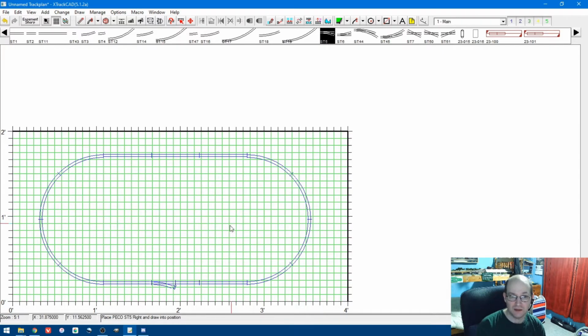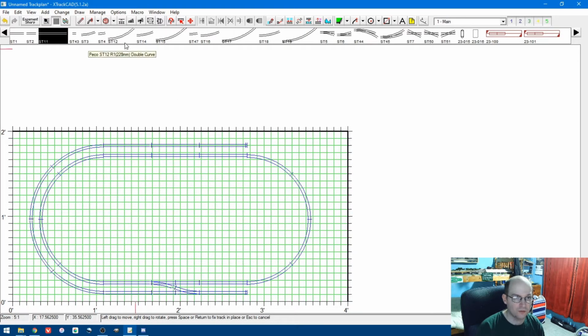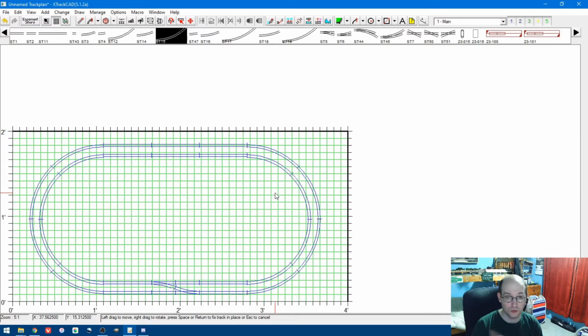You can actually do it a bit simpler way. You click on there, then you hold shift and keep clicking till it connects to the right connection point. And you can do that with every single piece. With straight track it won't really matter because it's only got 2 connection points. But you can also do that with curves. So if it's pointing the wrong direction, hold shift and it's now in the right direction. And it will continue holding it in that direction. Ooh, one more. Till there we go. And now that's a complete two loop layout.